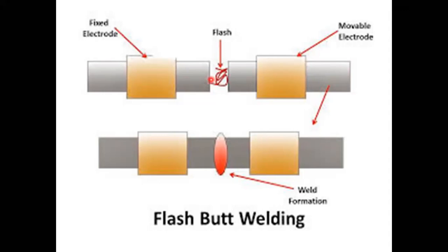But in flash joining, we apply power before the circuit is completed, or the path of current flow is completed, or you may say whenever the two electrodes are apart from each other. Okay, so for the procedure and construction, you can see this is the electrode, and this is actually a clamp. This is a clamp type electrode, and two materials are joined together.